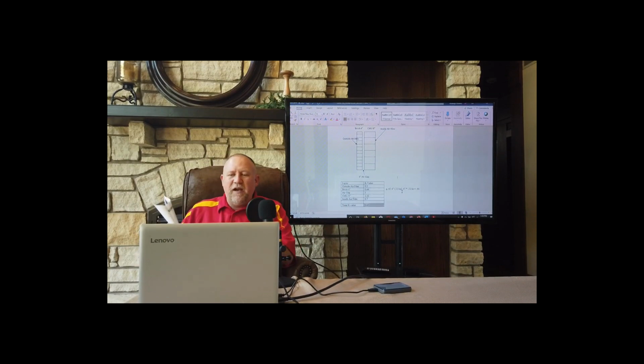If you go down to the very last entry on the second page of the handout, it says brick, comma, face, has an R value of 0.11 per inch. So then you multiply it by a 4-inch face brick.